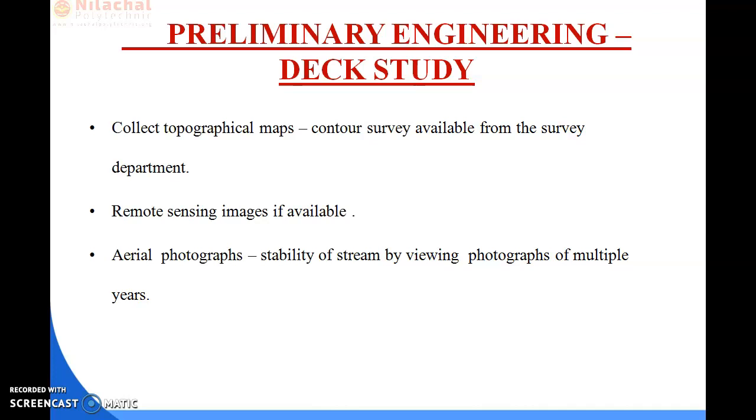Next, we discuss the characteristics of an ideal site for a bridge across a river. What are they? A straight reach of the river, steady river flow without cross currents, a narrow channel with firm banks, suitable high banks above high flood level on each side, rock or other hard inerodible strata close to the riverbed level, and avoidance of excessive underwater construction.